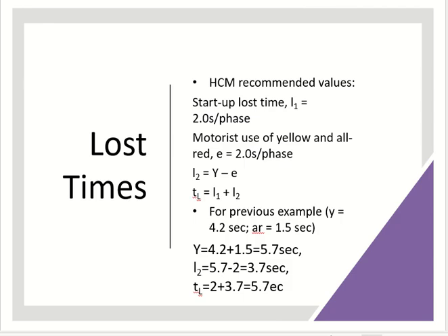Clearance interval is just all red time. Clearance loss time also includes the last part of yellow. So before all red it is yellow, right?